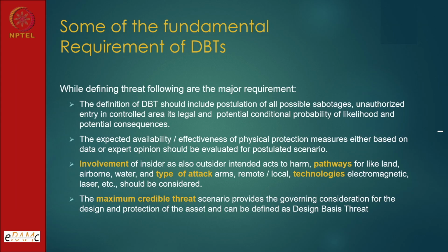evaluated. If data is not available, as we talked earlier, then expert opinion, and we will be discussing later in topic 4 or 5 the Bayesian updating. I have my own data which is limited, but I can use some mathematical technique to combine the generic data available in the open domain with the plant-specific data, and to have an estimate of it. And as the plant sees the operation period, we will know how well our data was, and then go on updating that database.